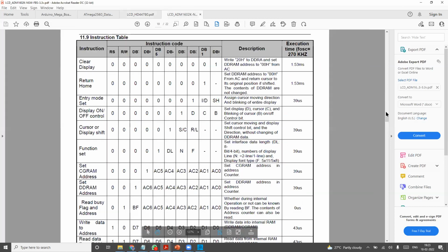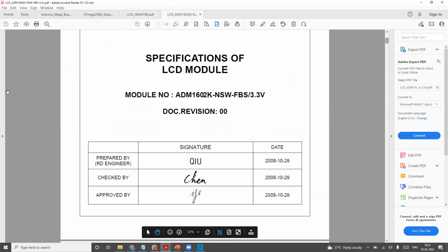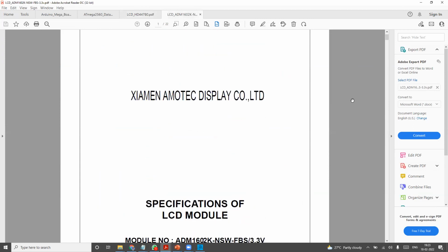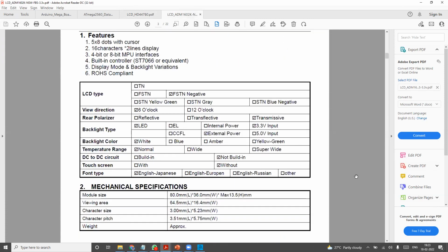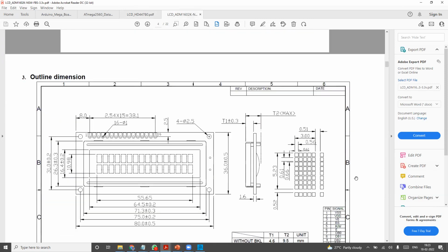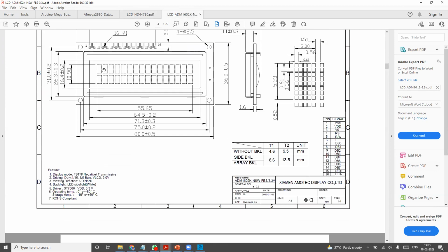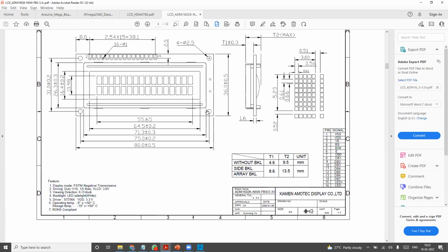See here, I have an LCD controller. This guy mentioned here, see, this is 16 by 2. And he has given the display size, the pins, the connector, you have to solder everything. And the dot matrix is this much, 5 by 8. See that? 5 by 8. Each dot size, everything has been given to you. So if you see this page, you will understand the display size.